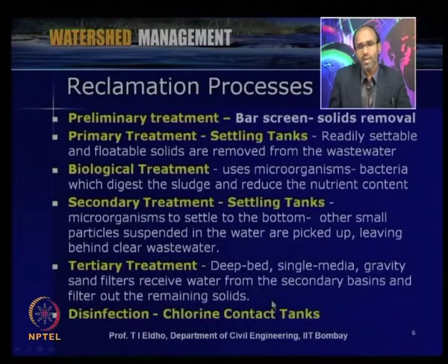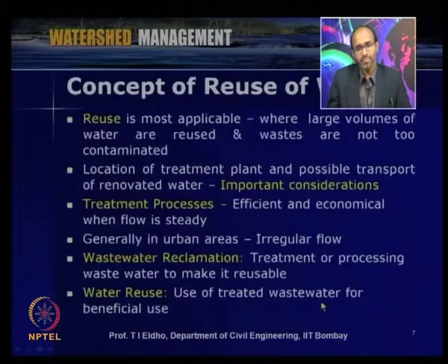We can mix the water after the tertiary treatment with chlorine in contact tanks, and that way we can disinfect the reclaimed water. So, that way we can directly reuse the water, even sometimes for potable purposes, if sufficient potable water is not available in the considered area.